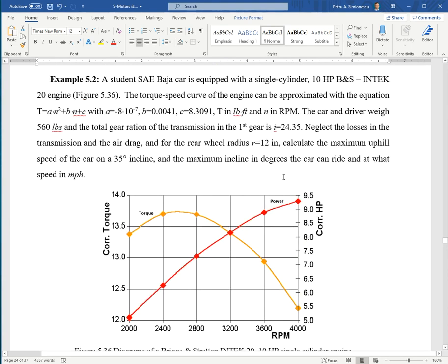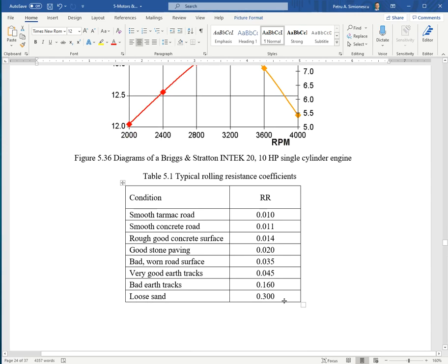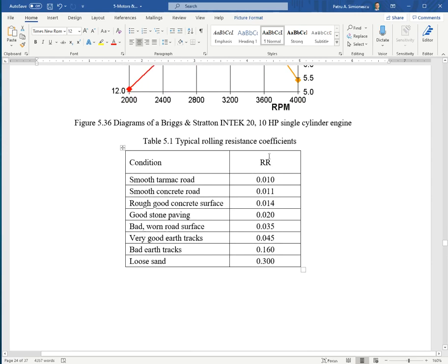There's some information. We have the coefficient of rolling resistance. Here are some typical values. Rolling resistance is resistance to rolling of the tires, they deform. Also the ground underneath deforms and comes back, but there's not 100% restoration or restitution of deformation energy, and that results in this rolling resistance. But we can work with it as if it were friction.